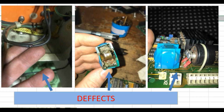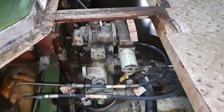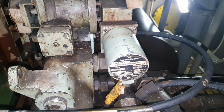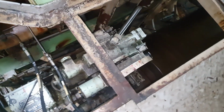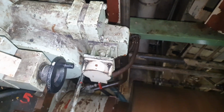There was a driver in spare parts and the electrician replaced it, but the system in follow-up control mode didn't work. Alarm "CPP control failure" still occurred. The system transferred to emergency mode. After working for a couple of days, this driver failed and then we continued to use the system in local mode, which I already talked about. Requisitions for the stepper motor, driver and electronic boards were made. I didn't want to leave the system in a faulty state and tried to restore the burned drivers, but unsuccessfully, because there were no suitable MOSFET transistors.